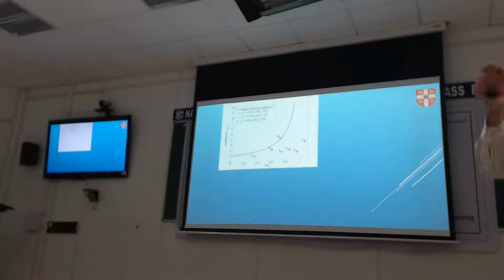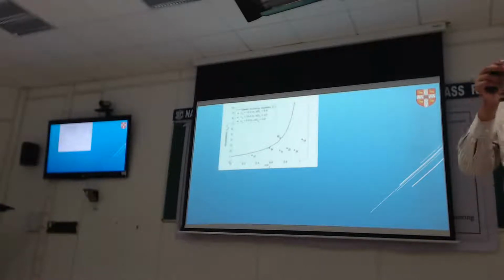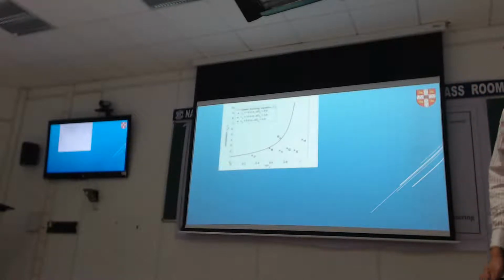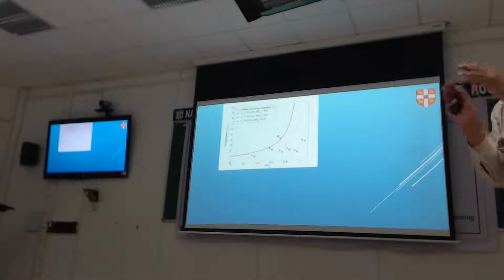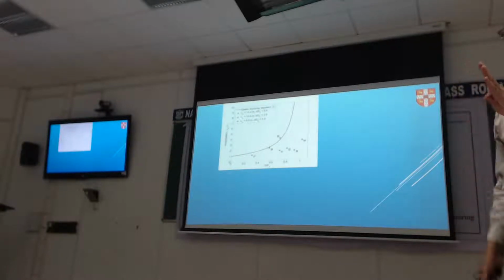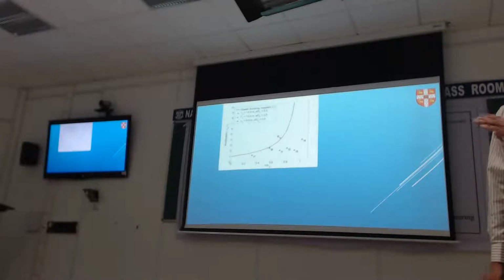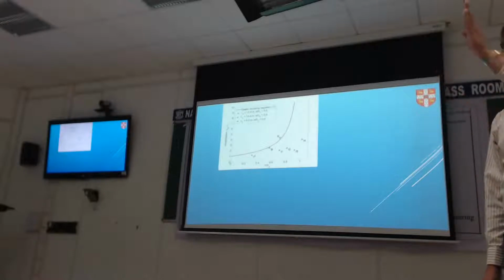Clearly when the earthquake is there, it's just oscillating, so the peak of that is going to be fairly small. That will be my delta naught. Delta earthquake has that oscillation plus the displacement due to buckling. So once I have this instability driving my pile head away, my displacements are taken and I'm normalizing that with just purely the initial displacement I get during shaking. So 1 means no effect of buckling, and the bigger the number, the more I ran away from my initial straight line.